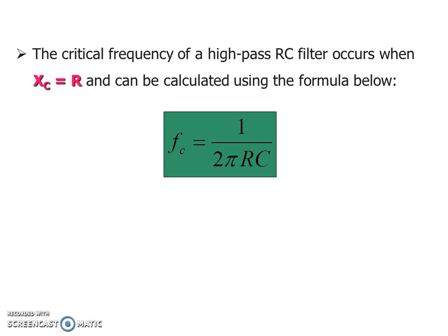Next, coming to the cutoff frequency, here we are designing a high pass filter, and we need to set up a cutoff frequency, where we will find the cutoff frequency and then go for the design of the R and C components. Basically, in the design of the low pass, high pass, band pass and band reject filters, C will be assumed as 0.01 microfarads and FC will be given in the question, in the design we have.